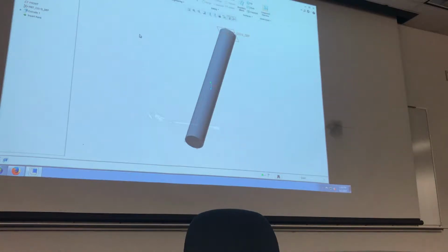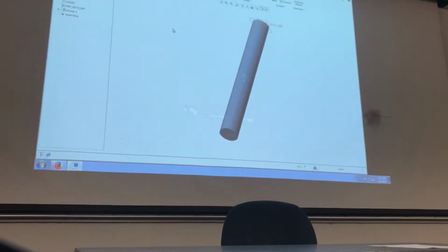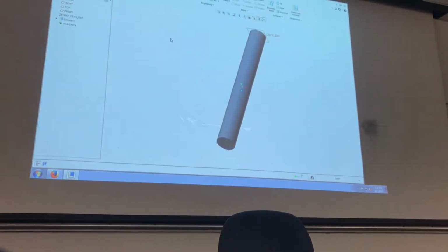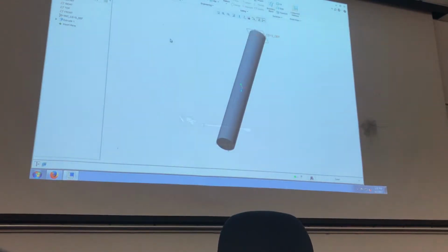One dimension, and now you have your screw made. You don't have to go through this every single time. So as you create screws, say you do the 1/4 20, you do a 5/16 24, you do all these other screws, save them into some sort of working directory. Okay? You can do the same thing for washers, so on and so forth, so that you don't have to recreate everything all the time. Okay? Make your own directories up.